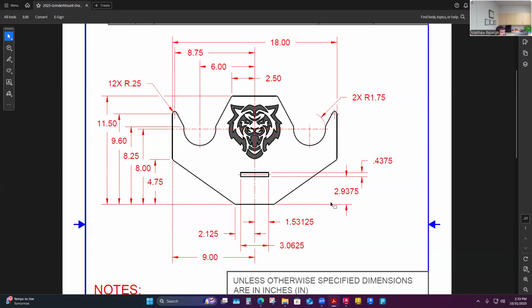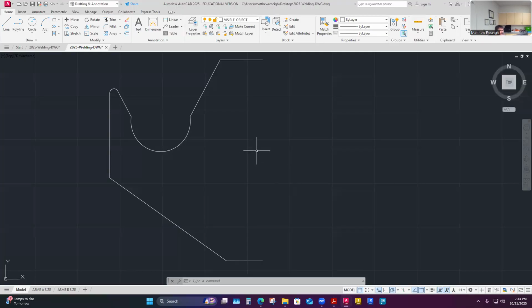The other thing we did in class is we joined it all. What I want to show on this, going back to how I built my boundary, and I showed you the difference between the rectangle and drawing a rectangle with lines, is that all this geometry we've drawn is each individual segmented lines, and they should all be connected, so the machine should be able to cut those without any issues. It's not going to tell us if they're not connected either, but this command I'm going to show you will tell you if you're not connected. So I use this to determine that my geometry is what I would call closed geometry. I know we don't have the other side of this yet, but I can even link everything together so that it's all one line essentially, or just one single selection.